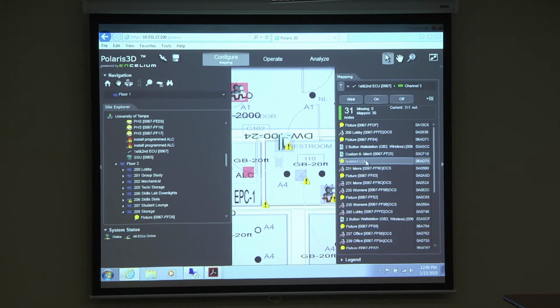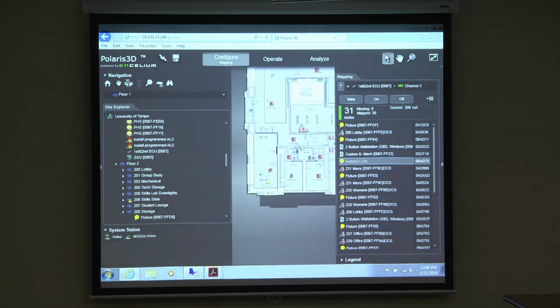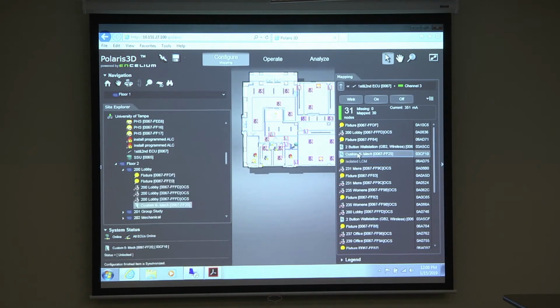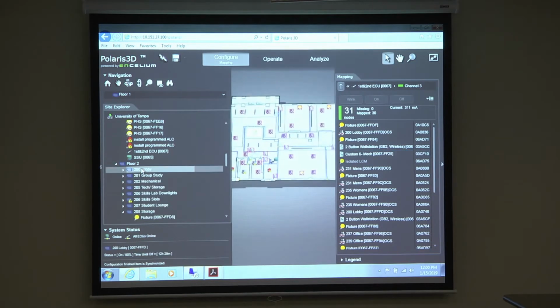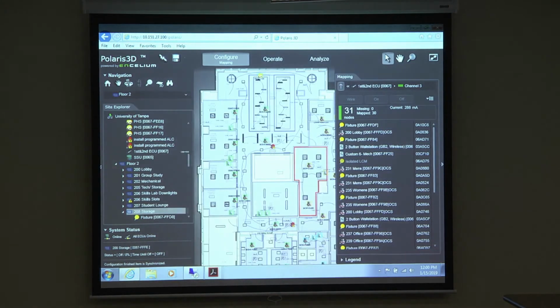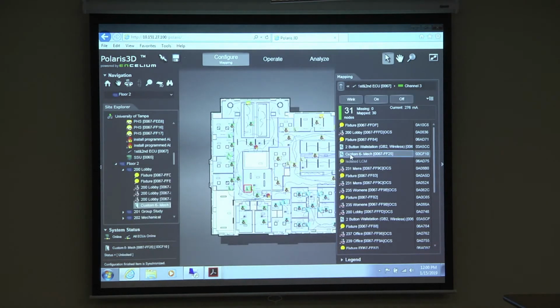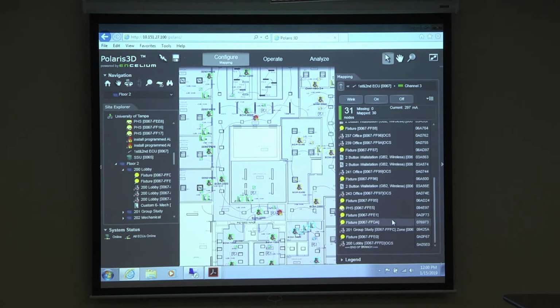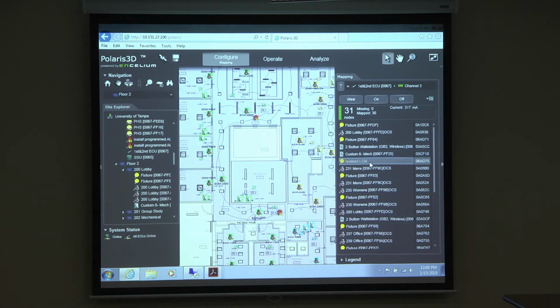That's this. If I click this module and I trigger it, I should be able to see what device it is, right? So if I zoom out of the floor plan, to get an idea as to where this device is, I would probably have to click on something that's already mapped nearby. And it's on the second floor, so go to this floor, for example. All right. And then something in the vicinity here is an LCM that's not mapped, right? So we can go through them. Anything that's not mapped looks like this one. It's just grayed out, right? And we can trigger them and see what they are, and then we can just program them. We can map them there eventually.